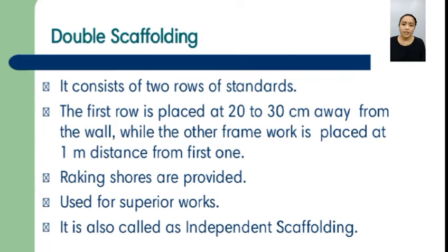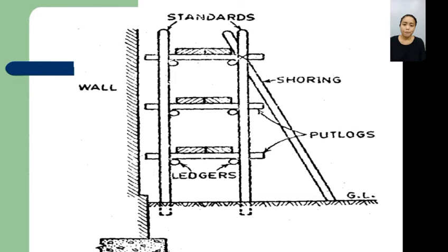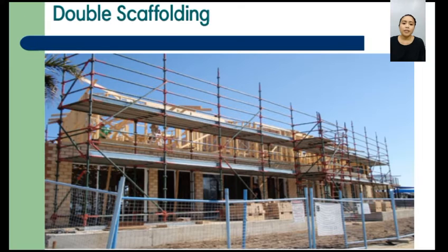This is a support system used by masons for plastering. It has pairs of inner and outer verticals. The footlogs, instead of being supported on the wall, are supported on the inner system of verticals and longitudinals to give additional lateral stability to the narrow and tall framework. It is tied to the building at intervals when used for a multi-story building.